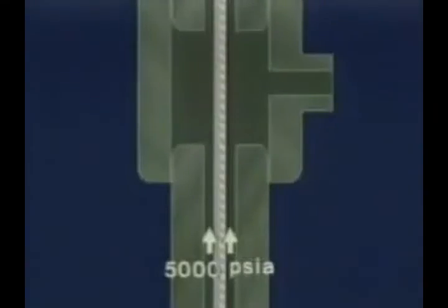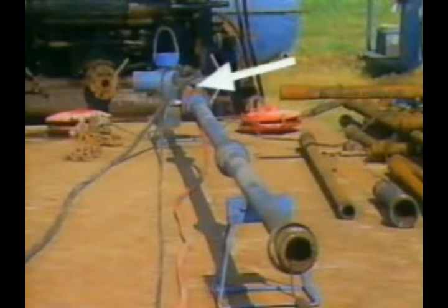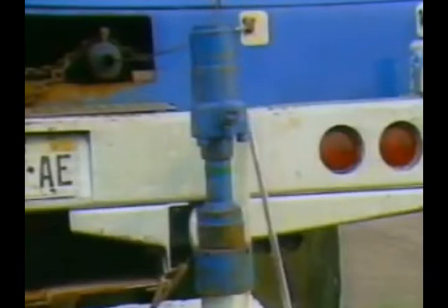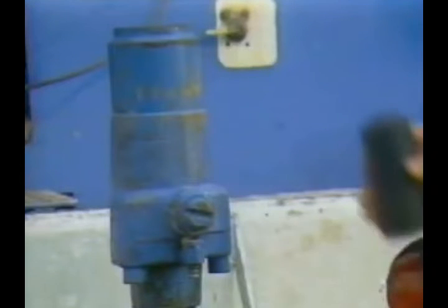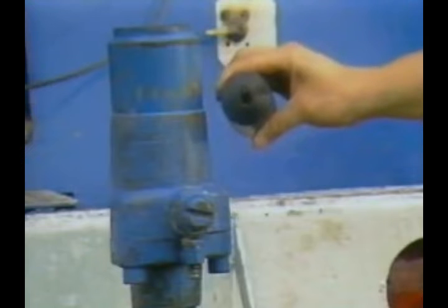The flow tube assembly provides the offsetting force which prevents well fluid from flowing out of the riser. When cable is moving into or out of the well under pressure, grease is continuously pumped into the small annular space between cable and flow tubes. Because the space is so small, the force required to offset the well pressure can be easily applied. At the top of the assembly is a hydraulically activated pack-off. The hydraulic pressure compresses a rubber packing ring around the cable in an emergency to prevent cable movement and seal up the assembly.